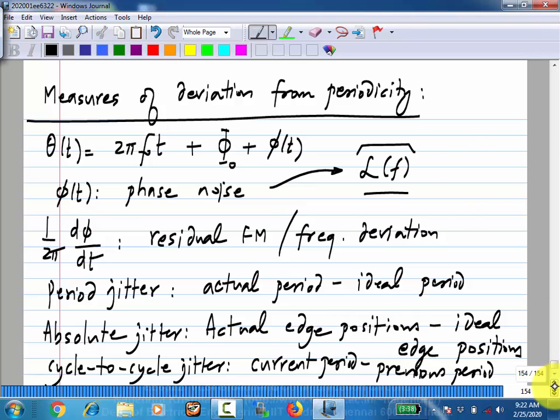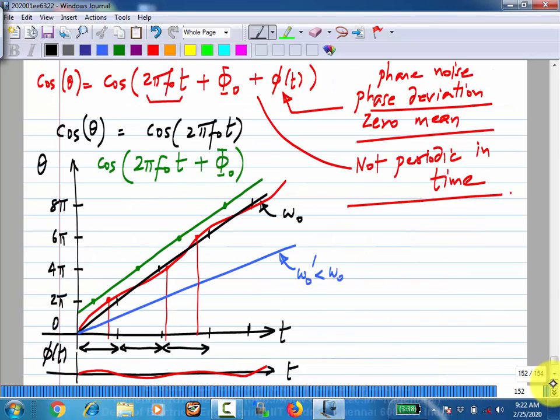Now one thing that we commonly do is to represent this phase, as I have done here, as a continuous time signal. That is, I have plotted theta of t where t is continuous, right? In reality, you can measure the phase of a signal only at the transitions. That is, you have to mark off some value and you have to see when the signal crosses that value. Like for instance, you have a sinusoid and you see when it crosses 0. Maybe you can take either only one direction or both directions. But let's say you take only one direction, then the distance between them will be the period, right? So phase is inherently a sampled quantity because of this, right?